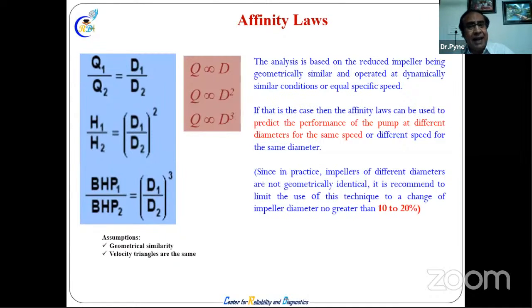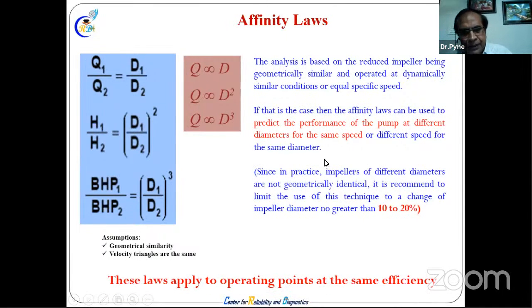And if you change the impeller diameter of the pump, how does it affect? A diameter change also affects horsepower like this. So we cannot do whatever we feel like. With a little diameter change, the power will be very much less, up to 8 times less. If you increase the diameter, the power is more. If you decrease the diameter, your power will be less. That is the way it is done.